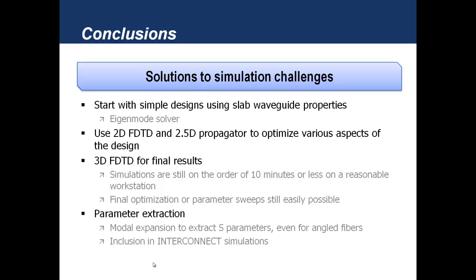And then for parameter extraction, we use these modal expansion monitors to extract the S parameters, and we can do this for angled fibers. That allows us to include these results in INTERCONNECT simulations, where we can do these frequency domain network analyzer simulations that allow us to look at the S parameters of the overall circuit. And we can even use this information to do time domain simulations and look at signal integrity analysis as well.